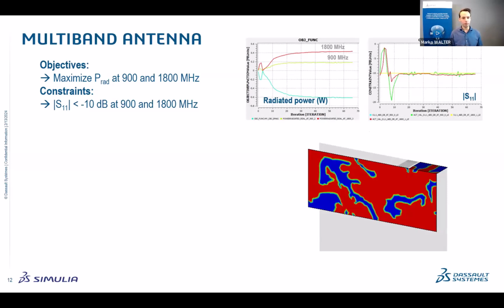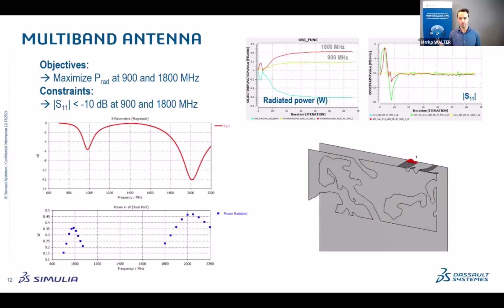And you can see then the radiated power again, 1800 megahertz and 900 megahertz going up. And the thing is, you need to verify these results again because, and I'll explain this in a second, basically you want to specify some threshold for the densities. These intermediate densities are going from vacuum to the conductor. To cut something out, to get some ISO cut, we refer to it, to extract the specific topology. And this threshold can also vary, and I'll talk about that in a moment.